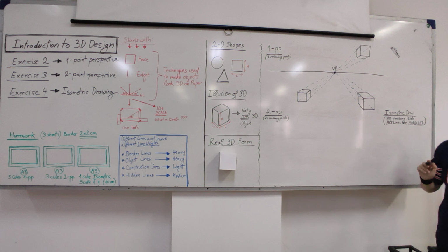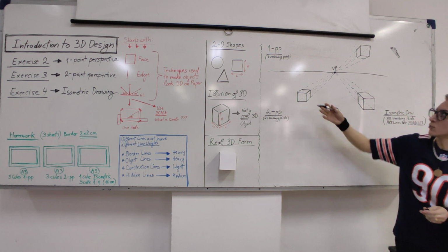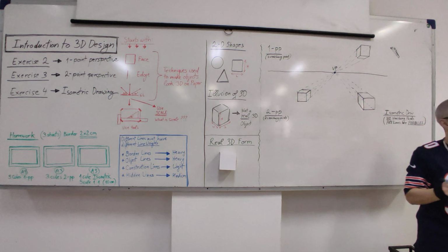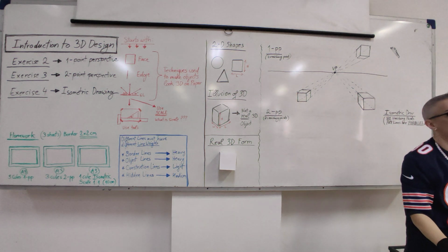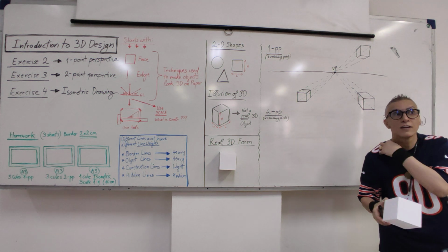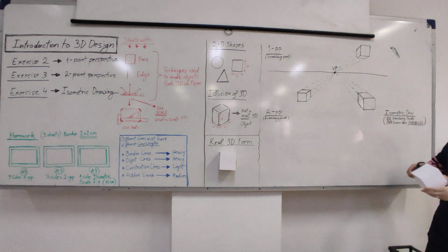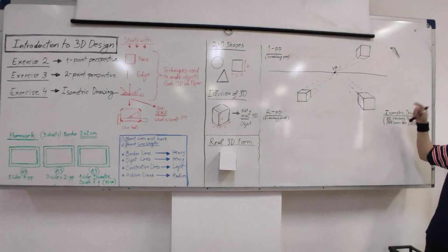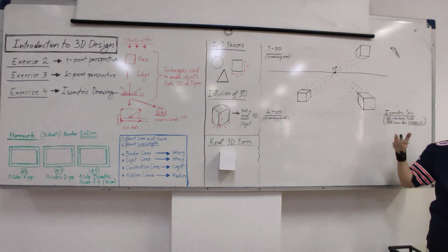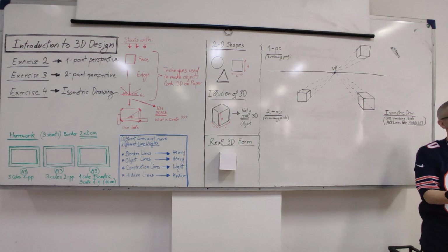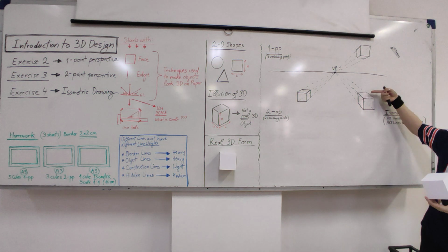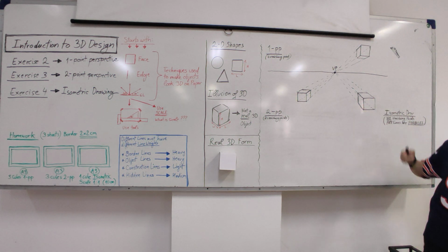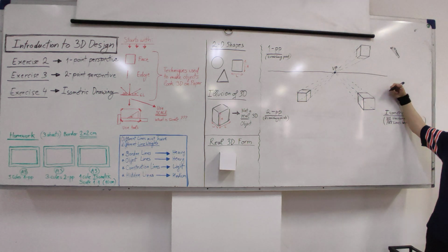Now, we are not finished, okay? When you look at this object, it is basically the cube. It's finished, completed. But I want you to draw also the hidden lines. What's a hidden line? When we see the cube, we see it really like that. But if you imagine it to be made of glass, we will see also this line here inside, and we will see this line. So this you also need to draw.